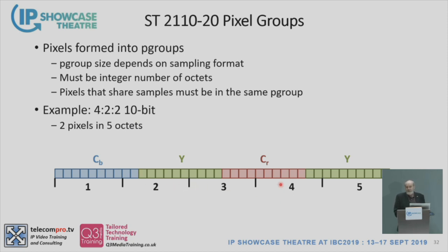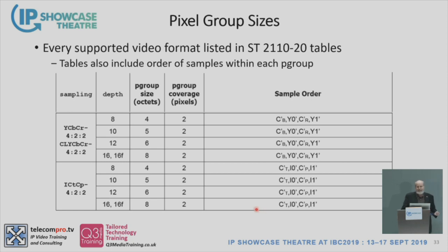Now you might say, geez, this is a little hard to calculate. How do I figure out what size my P group is and how many pixels are in it and everything like that? Well, don't worry. Right in the ST2110-20 standard is a table that gives you all of that information for every kind of video format that we could think of. And there's literally dozens of different formats in there that can be accommodated using P groups and therefore placed into ST2110-20.